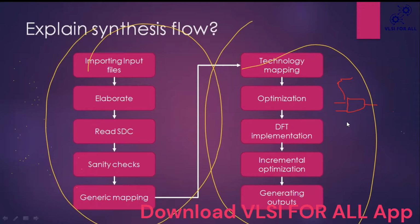During incremental optimization, those scannable flip flops will generate more delay compared to normal flip flops, so some timing may be affected. Area also gets added because of some extra small logic, mostly muxes, added in the design. Some area will increase after DFT. So again we have to bring the area, power, and timing to meet our target.